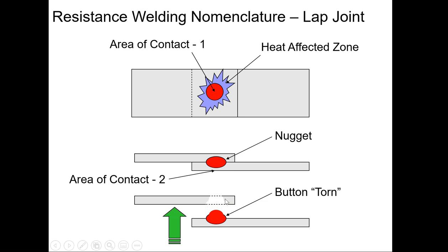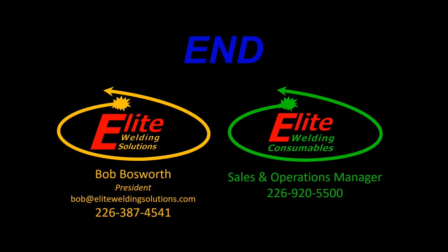I'm very interested in always knowing what the heat affected zone looks like, because you could have a fantastic weld in this area and you could have a lot of brittleness in the other areas around it. And this brittleness will cause things to crack.